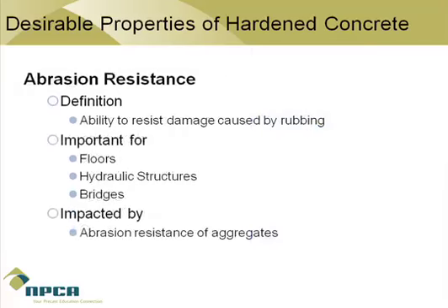Now, how about abrasion resistance? What we're talking about is the ability of concrete to resist rubbing. Some examples of situations that may cause abrasion to concrete are traffic from motor vehicles or people walking across a concrete floor in a busy walkway. Water running over concrete can also abrade concrete surfaces. Precast concrete can be made to be very resistant to abrasion by using quality raw materials and proper manufacturing and placement practices.